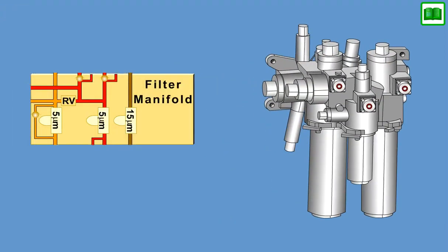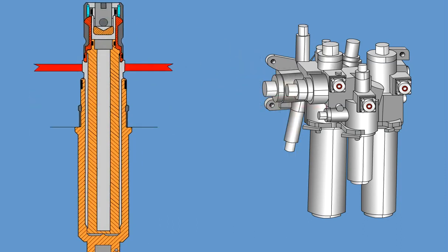Hydraulic fluid pressure and return flows are routed through identical separate 5-micron filters. The EDP case drain flow is routed through a 15-micron filter. Identical pressure and return filter elements were used to reduce the number of sizes of filter elements required to maintain the aircraft. The filter manifold assembly contains an automatic shut-off device for each filter location to prevent fluid drainage when the filter element is removed.